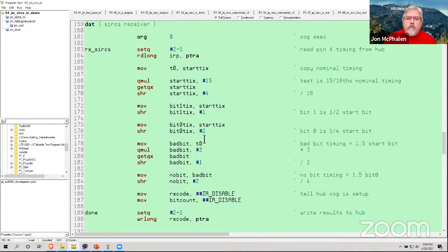Now getting back to this and why I was talking about measuring timing, when we have a TV remote, it's pretty low bandwidth. We're pressing a channel or we're doing something, but out when we're playing laser tag, these things can shoot 800 rounds a minute. And now imagine you have 100 players that are all shooting at each other. That's lots of IR signals. And so what the taggers have to do from a reliability standpoint is measure all the bits coming in, because if we have two signals arrive coincidentally, they're going to get scrambled, and we don't want to misinterpret that.